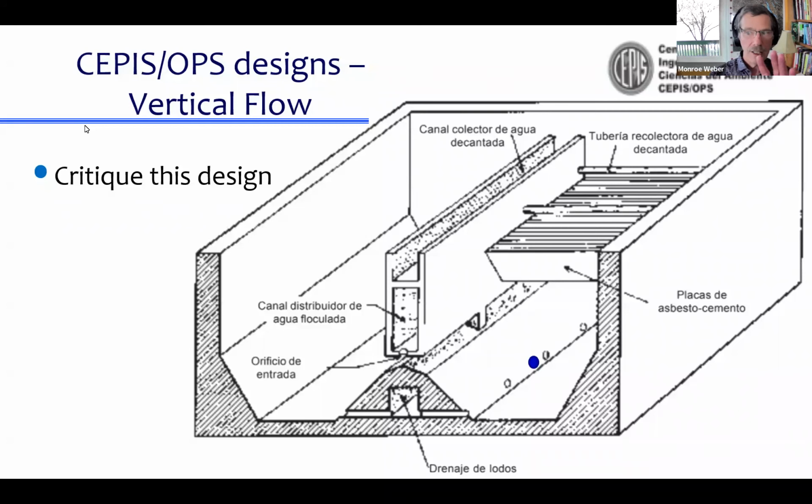So the question about the launders. It seems like the launders, or the effluent manifolds, you can see two of them there. I'm not sure if this drawing is completely correct according to their design, although it might be. We can look at a picture in a second. And yes, you do need to keep the distance between those effluent manifolds not too far apart.